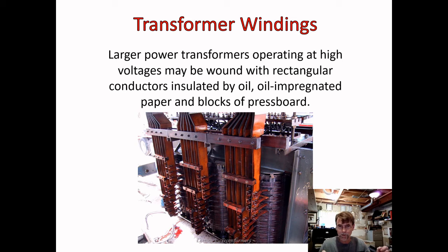When you have two pieces of wire and you hold them just a short distance apart, air is a very good insulator. Okay, but at some point there's going to be enough voltage to push the current across that air barrier, and that's what we see as a spark. So the same thing is true for any insulation. If the voltage is high enough, it can defeat the insulation and push the current through it. So in our high voltage transformers, we have to work a lot harder to make sure that we have that insulation value. Okay.